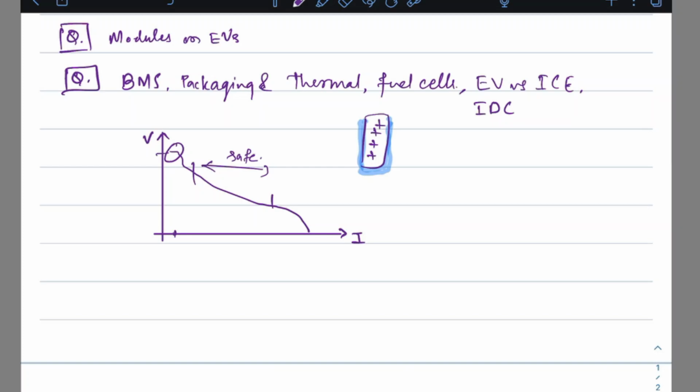each lithium-ion cell would give you around 3.3 to 3.7 volts, right? But you are running your systems at say 24 volts or 48 volts or even higher voltages. So you are connecting them in series, a bunch of few cells connected in series. Then one series is not enough to give you sufficient current. So you add more such branches in parallel to create a bigger battery pack which will meet your voltage and current requirements.